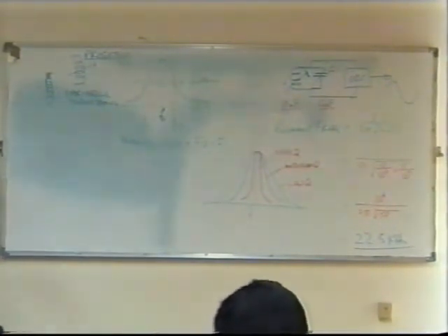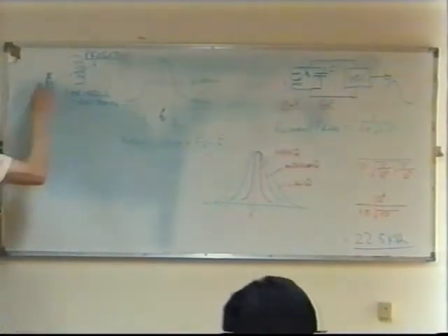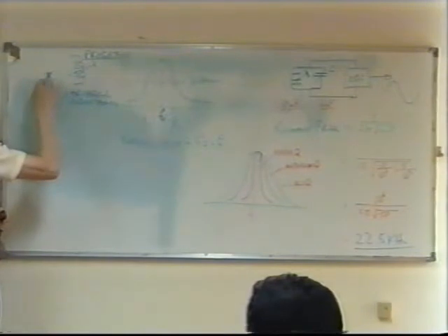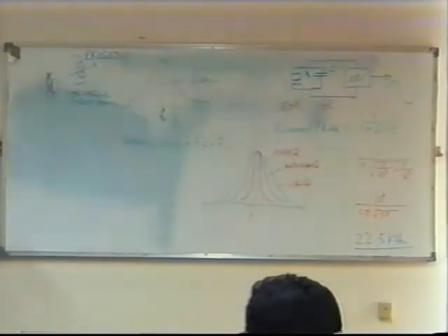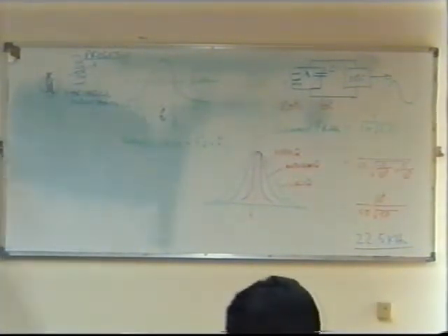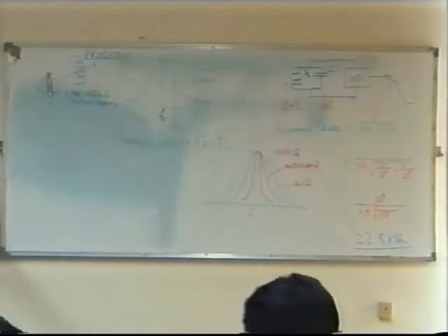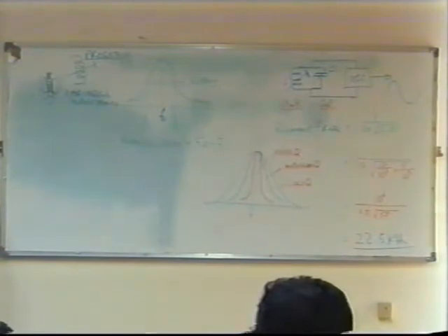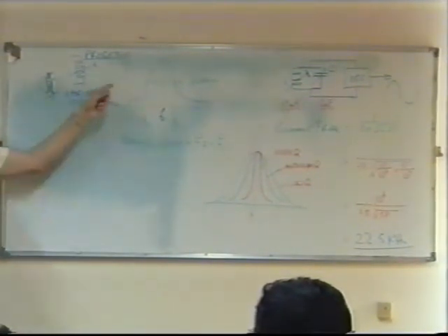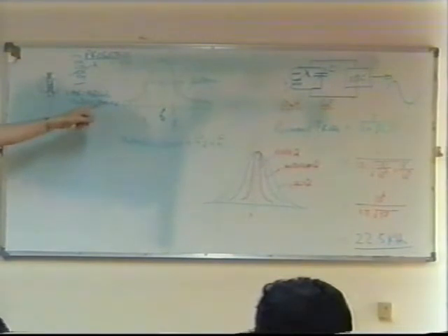There's another problem as well when this produces magnetic fields. As you know, the magnetic field is produced around the coil like this, isn't it? Remember? Now, for a radio frequency coil, that magnetic field can radiate energy and can influence other components in the circuit. There are two effects of this. First of all, it can interfere with the rest of the circuit, which is something you don't want.